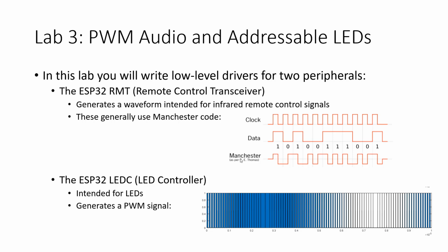So your choice is you could use something like UART, where both sides just agree on a clock, but that would be very slow and also would be even more unreliable than UART, considering that it's a wireless technology. It's infrared. Or you could try to extract the clock signal from the data signal, which is what PCI Express does. And as it turns out, that's the option they took for this. They use this thing called Manchester encoding. And so basically the way it works is to encode the signal in Manchester, it's very simple. You just have a clock and you XNOR it with the data. Done. Very simple. However, to decode a Manchester encoded signal, that's tricky.